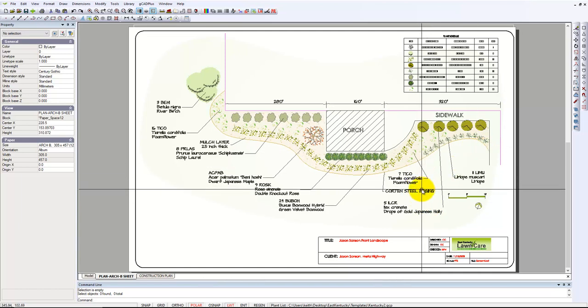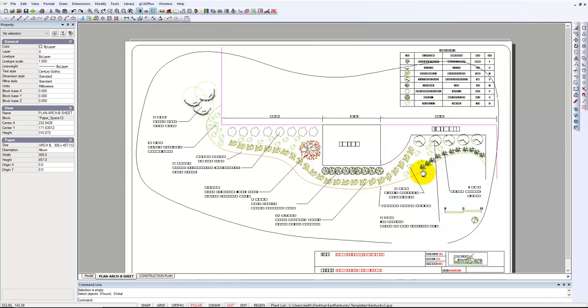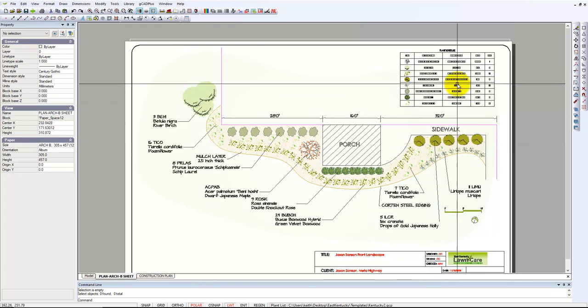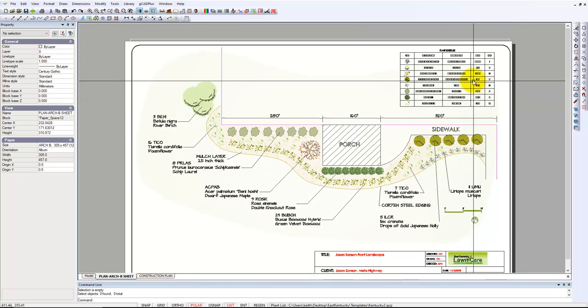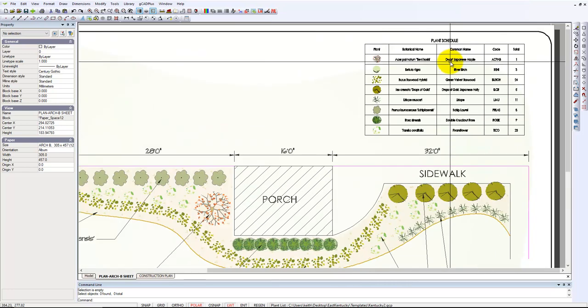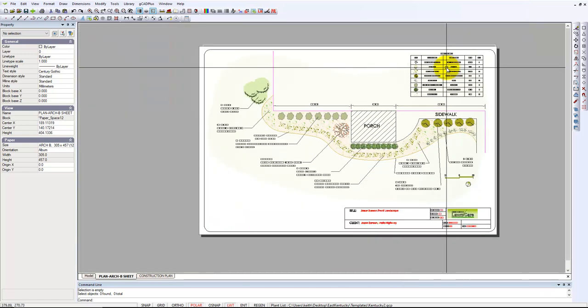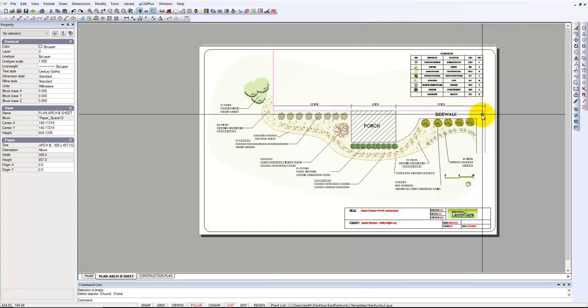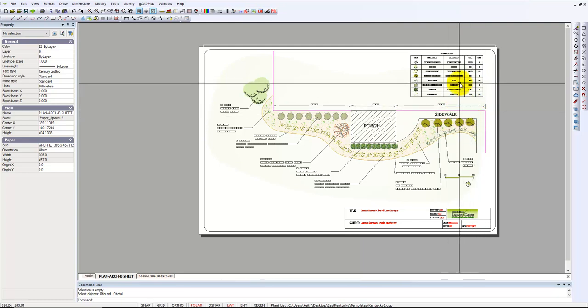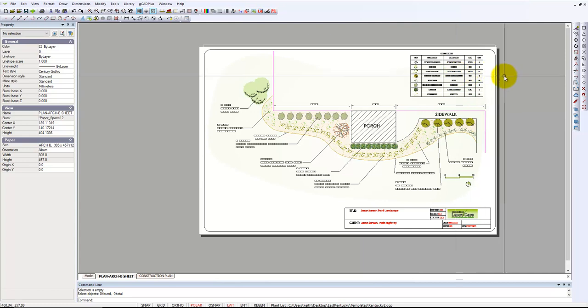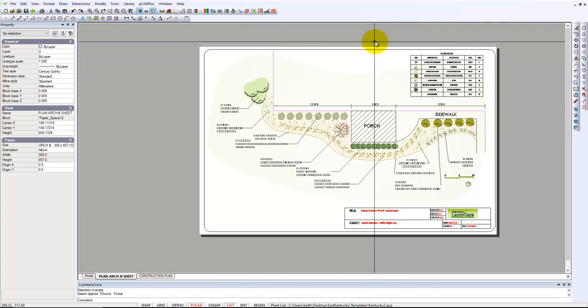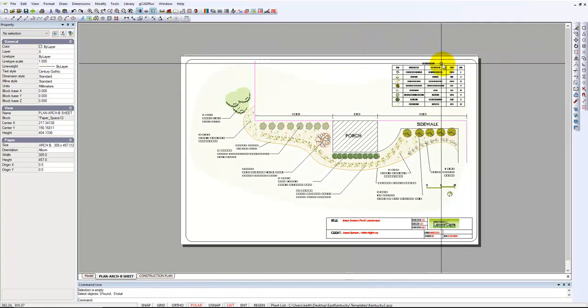But they're also having trouble with the positioning of the extra floating viewport that gives you the plant schedule here, and they're finding it's difficult to select, in part because the filled polyline wash is now on top of the plant schedule floating viewport. So a new viewport has been added, and it's a little bit difficult to select. If I just try clicking, that's rather awkward.